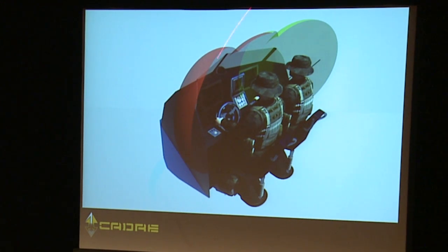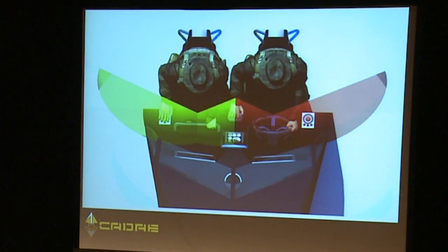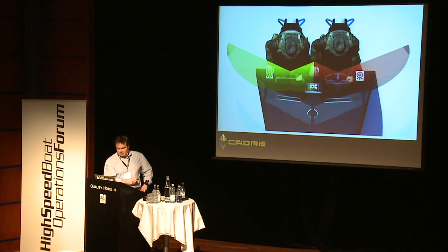So we then drew in these arcs, and it's more obvious from above. So this is the range that they can actually reach to. Things that you need to do all the time need to be put inside of this. Things that you may use less often may be put outside of it, but it gives you an indication of how close things need to be to the people.